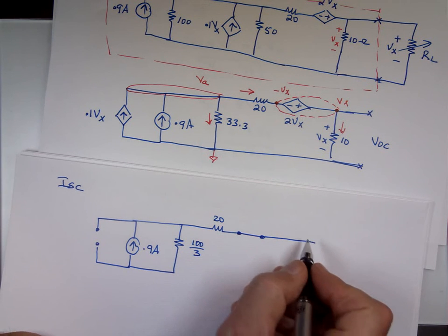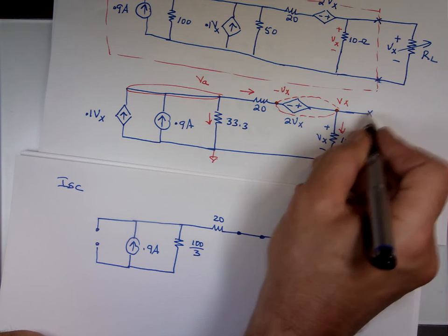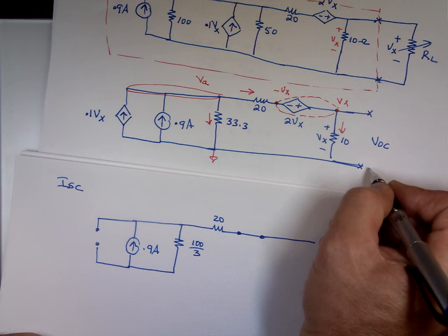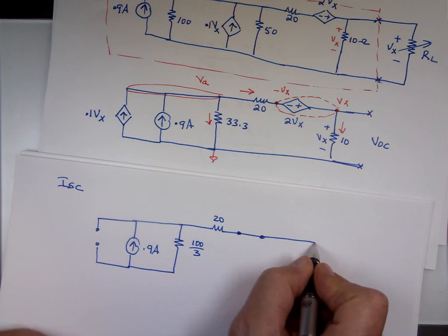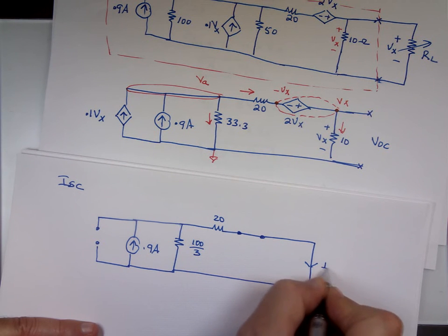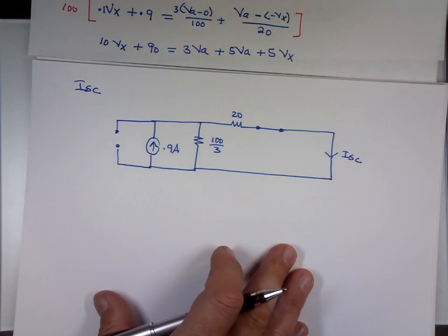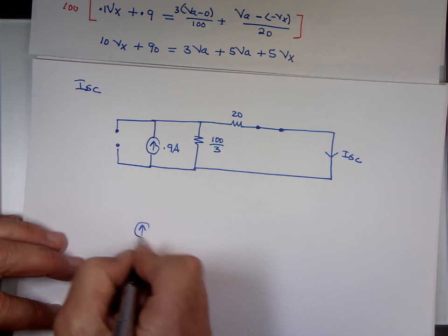And what's going to happen to that resistor? Gone. When you put a wire here, that resistor is gone. That's in parallel with 0, yep. And that's my I short circuit. That resistor is gone. Guess what? It's current division. That's it. You look at that circuit, it looks like this. If you clean it,